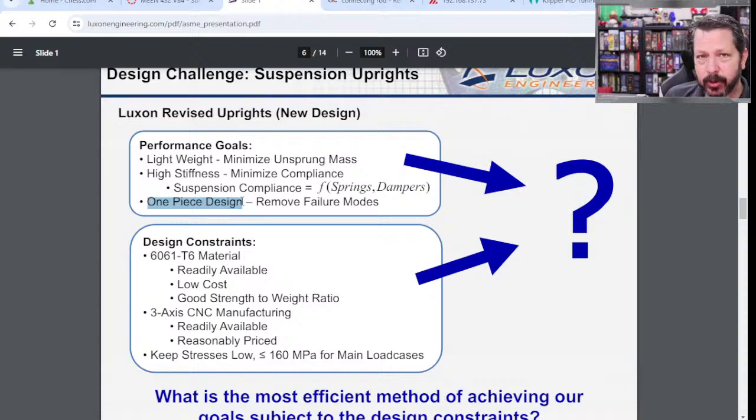It doesn't make quite as much sense because you can still create the part and just make it hollow inside, so have a lighter weight infill, more walls, that kind of stuff. So you can lightweight things a different way with FDM printing than you can with some of the metal 3D printing, although you can sort of make metal parts hollow. You just have to be careful not to trap the particles. We haven't really talked about metal 3D printing yet though, which could be in a medical situation.